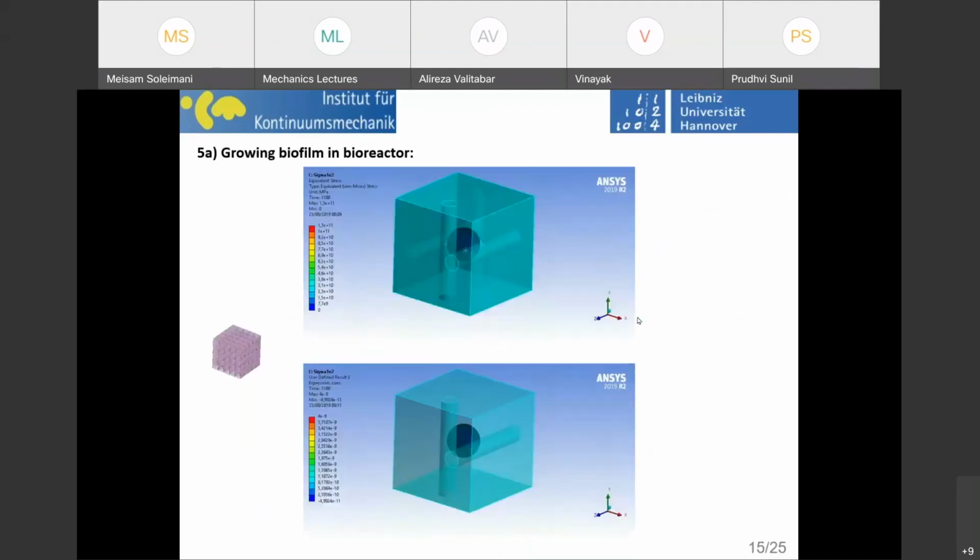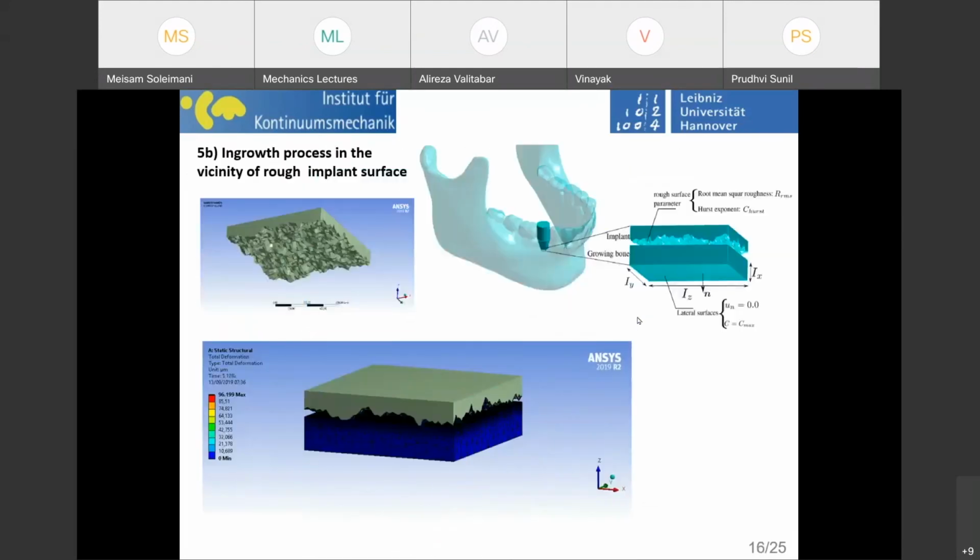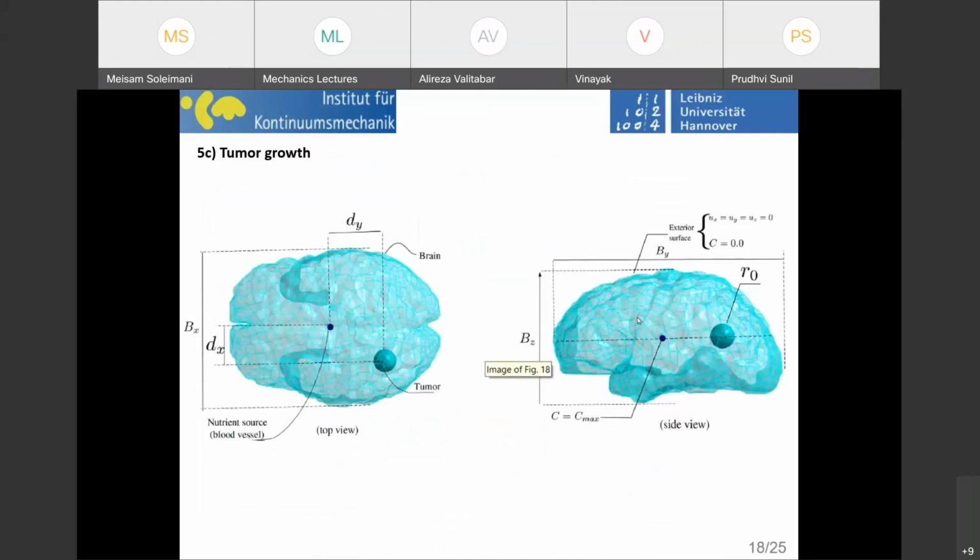You are talking about a tumor case, this one, right? Yes, of course. Okay. It's about the brain tumor. What I said is, what's the difference of this problem compared to the problem that I already discussed, that growing sphere in this cube? The difference is that here, the surrounding barrier is elastic, so it's not rigid. That means that upon growing, you start to develop some compressive loads within the tumor itself. Instead, you create some tensile stress in the brain, in the surrounding healthy tissue.